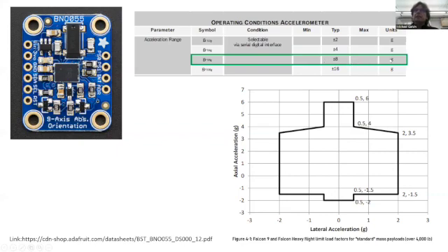The trade-off here is the smaller range that you use, the more precision that you get within that range. And so if you go all the way up to plus or minus 16 Gs, then you just get less precision. And maybe that's important for when you're trying to measure those very gentle decelerations during orbit or during reentry.